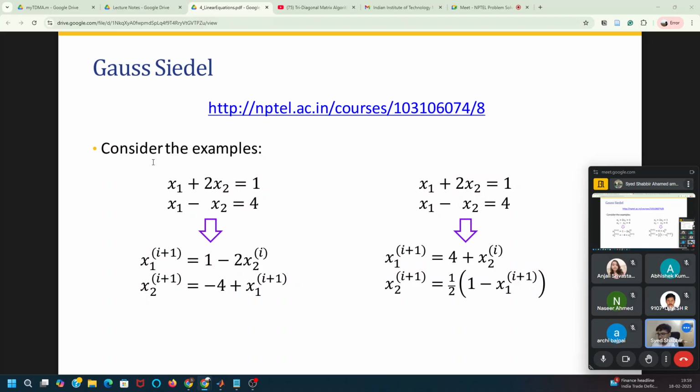So convergence in iterative methods should be a top criterion. If your solution is diverging, then the algorithm we are using is not suitable for the problem. You might want to change it, or there is some discrepancy in the input which you are giving.